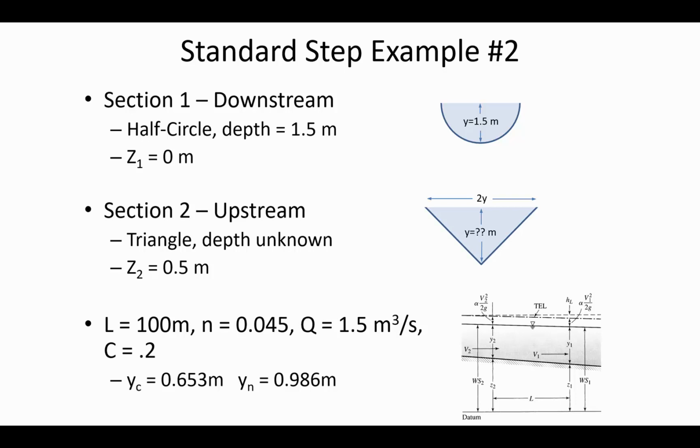Do you remember the decision criteria for classifying whether the flow conditions are mild or steep? Caleb says mild. You're right. And how do you know that it's a mild slope here, Caleb? It was a 50-50 guess. That's all right. If the normal depth is more than the critical depth, that's mild.